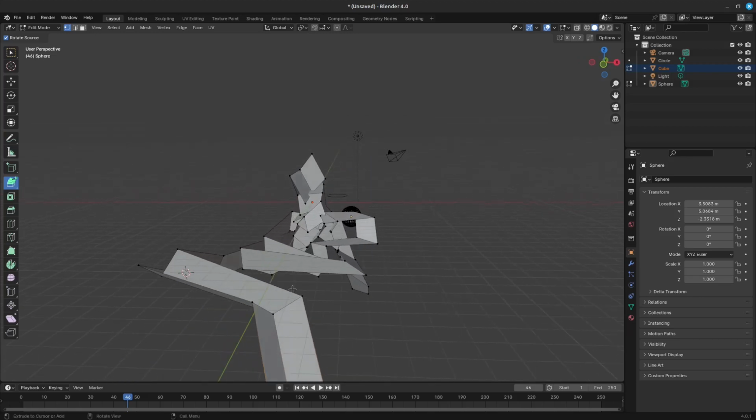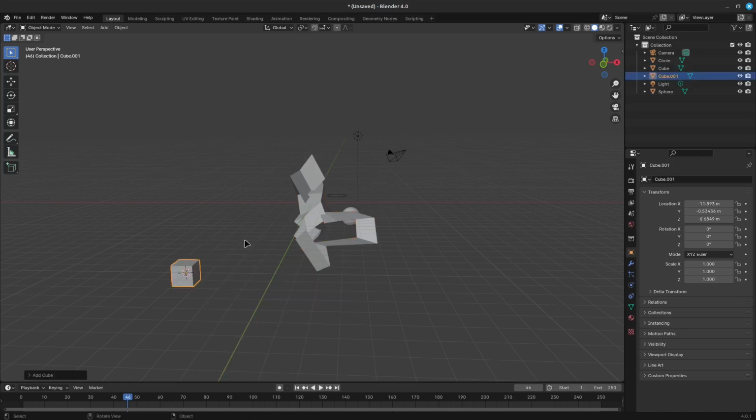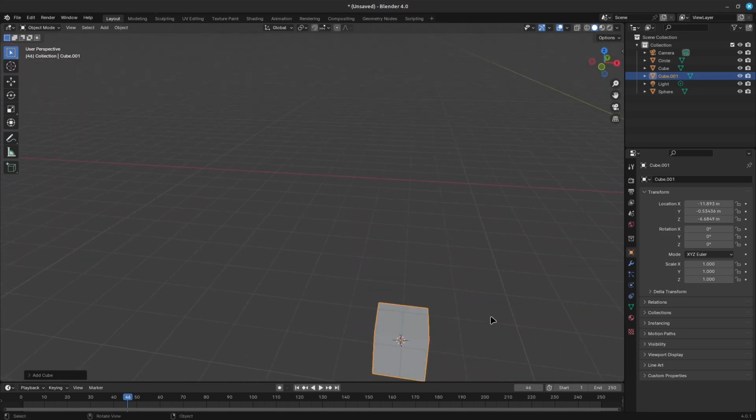With all of this said about extruding, to quickly add new faces to extrude, we can use the Loop Cut tool. The shortcut, if you didn't use the tool, is Control plus R. You can pre-visualize the cut before you make it, and then make a cut that will change face of the surface for more extrusion space.